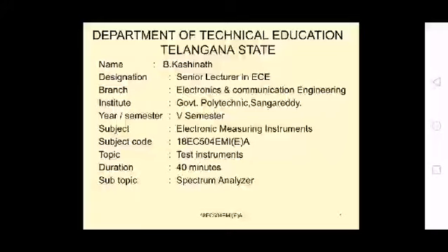The main parts of the distortion factor meter are the impedance converter, which is applied to your input, second your rejection amplifier, third the metering circuit, and fourth the power supply. The distortion factor meter has two modes of operation. When the switch is in the voltmeter position, it works as an AC voltmeter, which is used for measurement of AC voltage readings, or you can check the gain measurement between the output and input. When the switch is in position 2, it is connected to the distortion position. Then you can adjust your distortion levels by using the sensitivity control. That sensitivity control has a total of 50 dB attenuation in steps of 10 dB, so you can choose different amounts of distortion applied to the impedance converter.